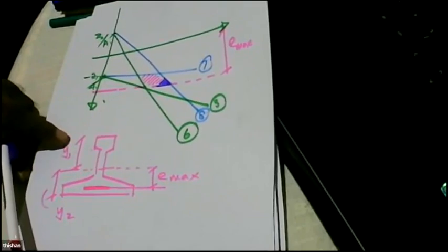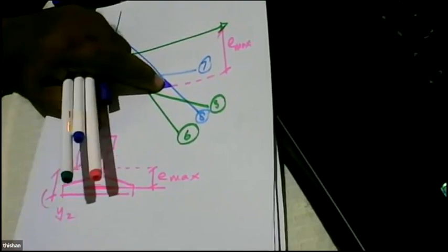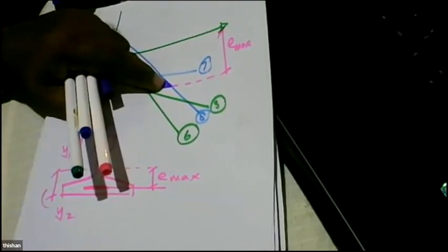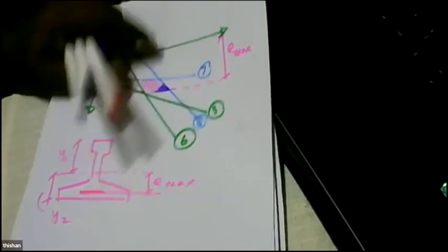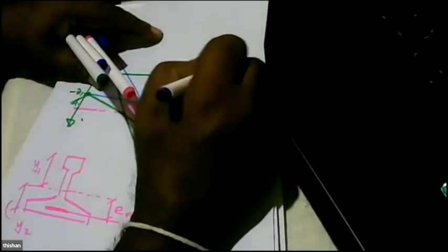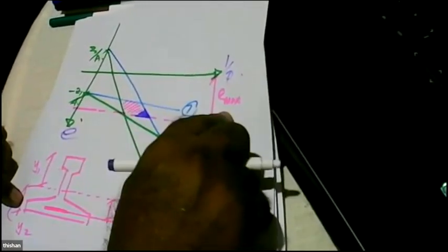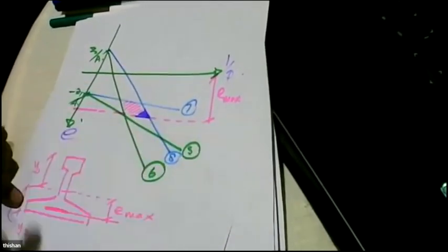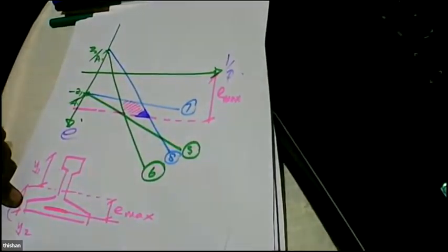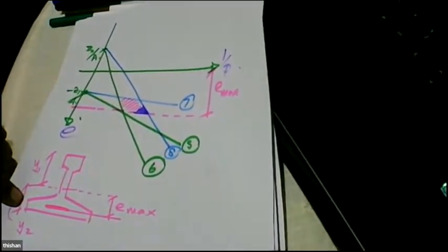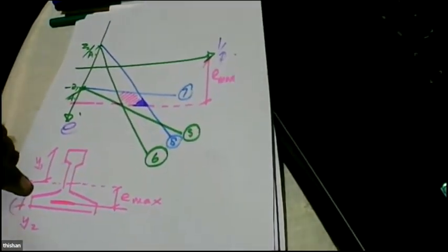And when you draw the Magnel diagram, we select the pre-stress as low as possible. And we come to this place because this is 1/P and this is e. So 1/P means the more we go this way, the lesser the pre-stress we can get. So that's how you find the pre-stress force by using the Magnel diagram for the composite section.